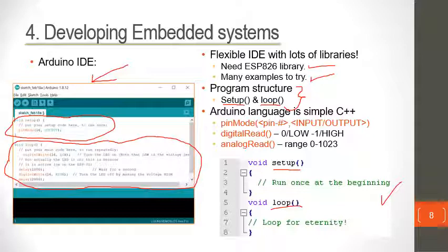it will have many inbuilt functions actually, which will be useful for us to program microcontrollers very quickly, such as, you see this one, which is called pinMode. This will be used to set the mode of a pin, if the pin being the input or output pin, or a leg of that microcontroller, to know how to interface it.